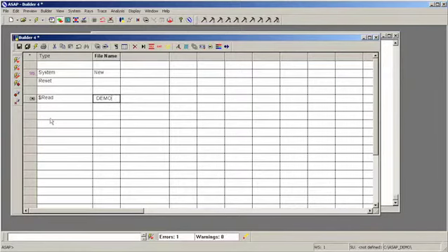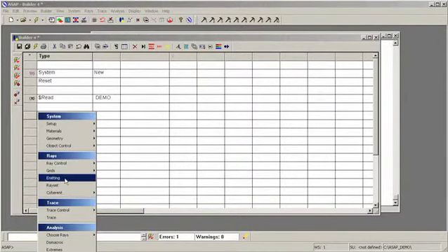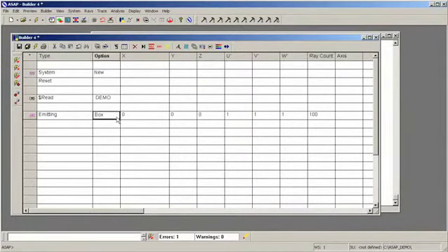Okay. And finally, we specify source properties. We go back into the menu system, raise emitting, and we use the emitting object option to turn that helical filament into an emitting object. Okay. Right here we have to specify what the name of that object is.